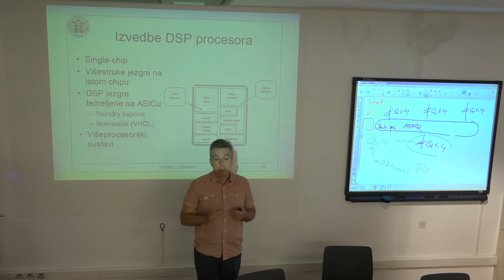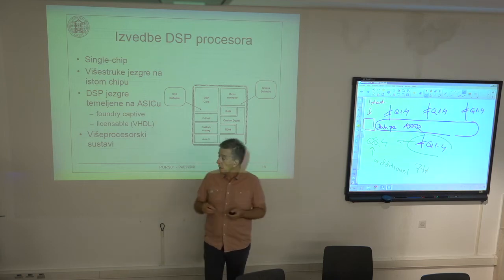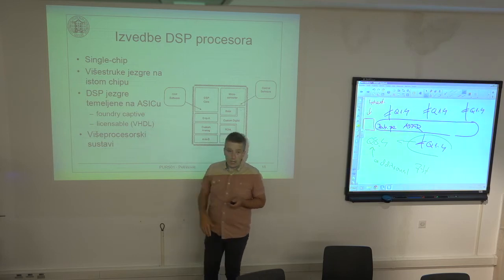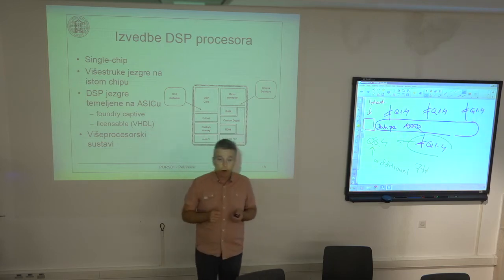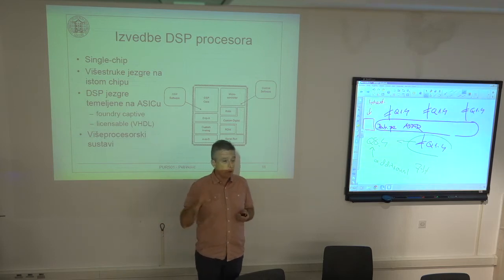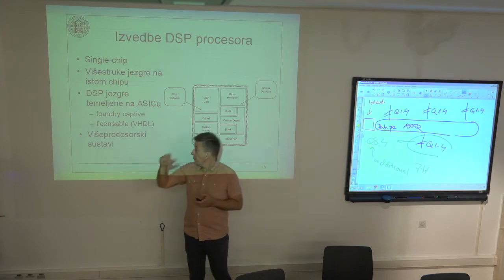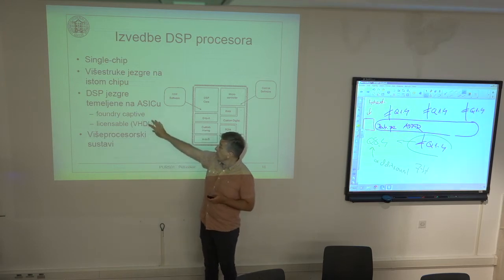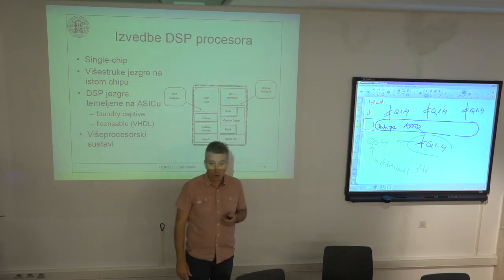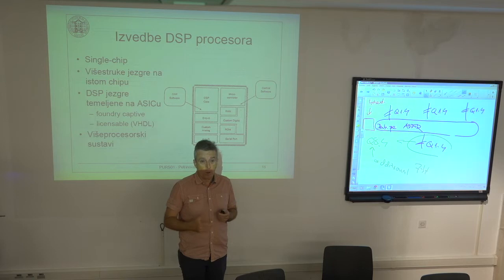So you have this whole system implemented by integrating several such IP cores. You take the main CPU VHDL model, IP core, you take a DSP, you take buses, bus controls, RAM, ROM, and so on, and you implement it all together in some ASIC design. You have a solution that is customized to your particular application.